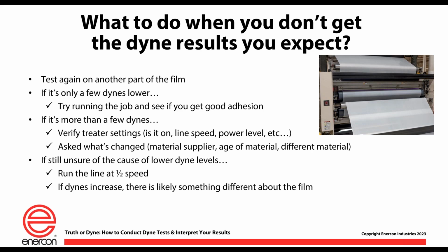Test another section of the film. Was there an area of the film that wasn't treated? Meaning they forgot to turn the treater on, or maybe the treater inadvertently shut off for some reason, or something of that nature. There was some equipment disconnection.